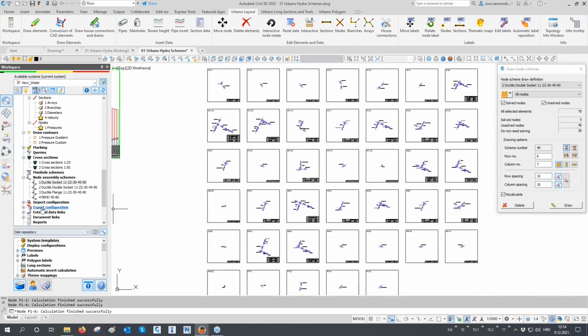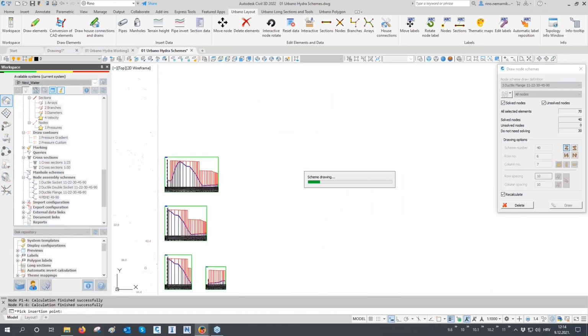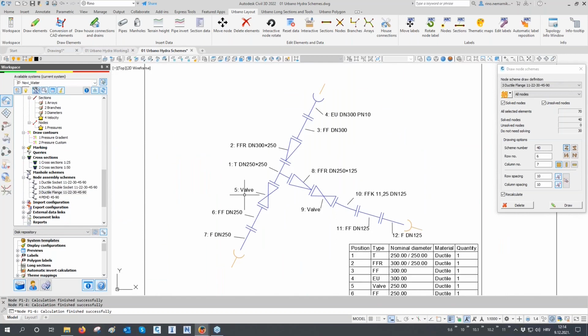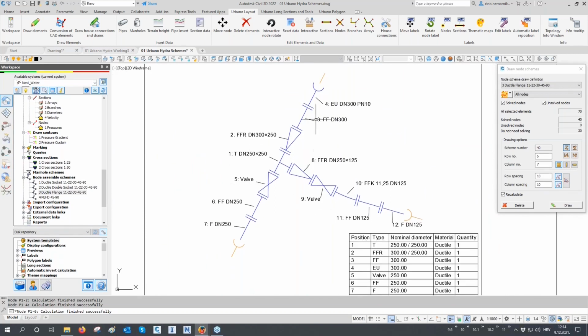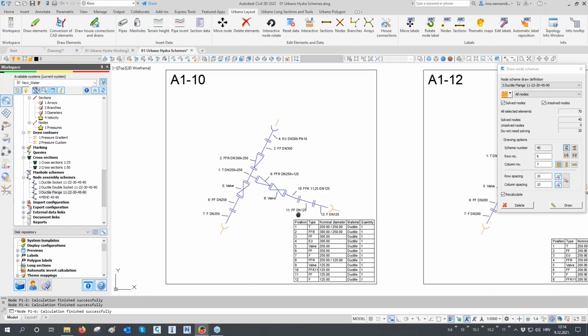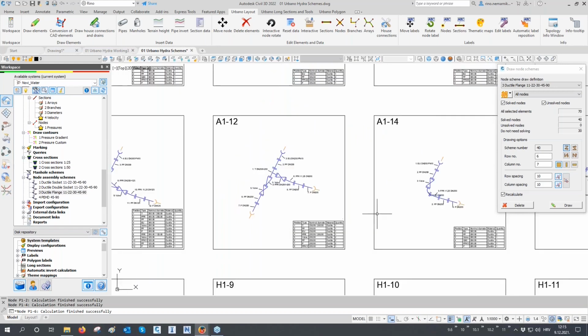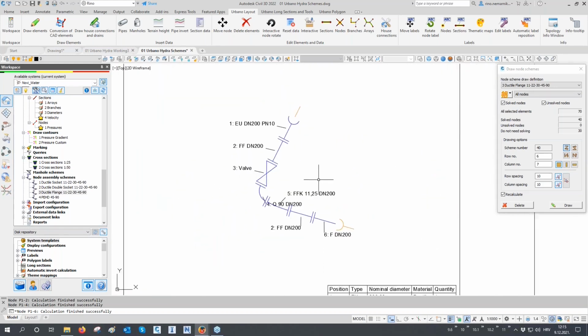And also, let's check the last configuration, ductile with only flange elements with all the angles. Let's select everything. Let's click on draw. Let's place it here. And now you will see that again, it looks completely different. This is maybe better style, better solution to use if this is happening inside of a manhole, because you have this entering piece inside of the manhole, then you have the reduction, the classic T-piece, the valves inside, the reductions, and then the parts where you are exiting of the manhole. And again, you have all the pieces that are calculated in the bill of material.